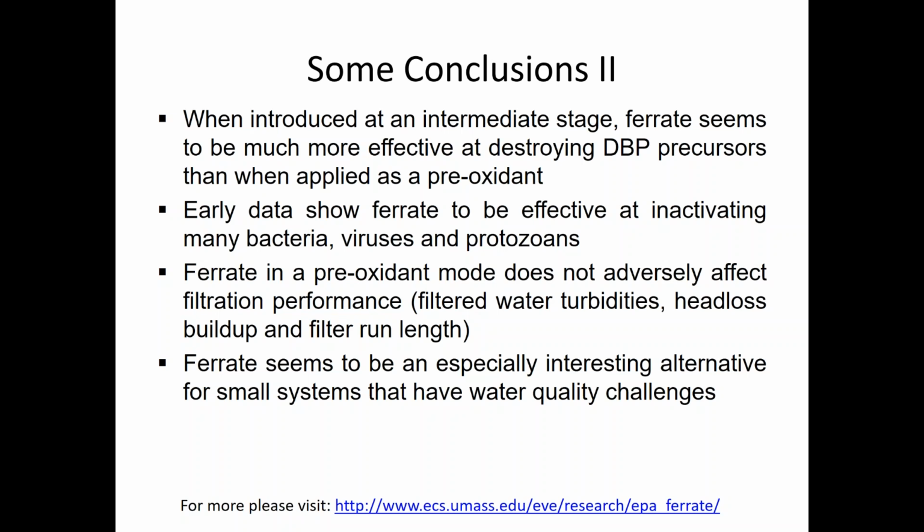Our early data show that ferrate can be very effective at inactivating bacteria, viruses, and protozoans, as I showed in some of the CT data, although we are waiting on the EPA to finish design and launch a CT study so that we'll get firm numbers for CT tables.